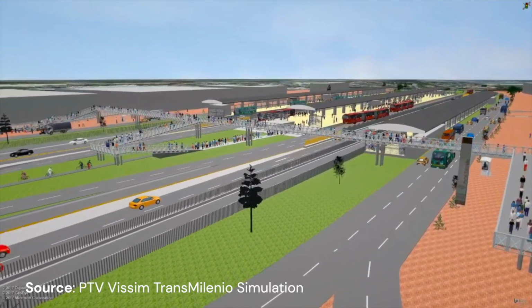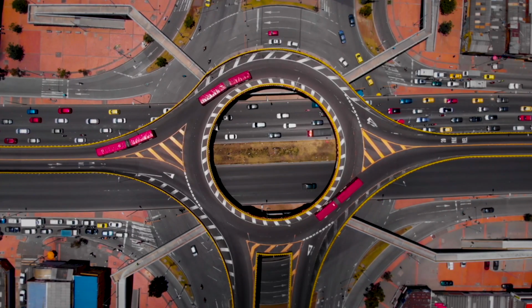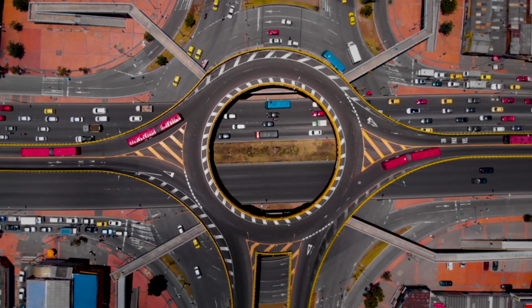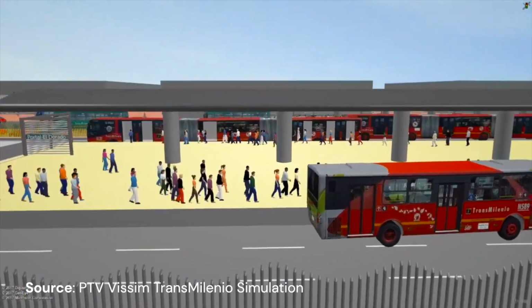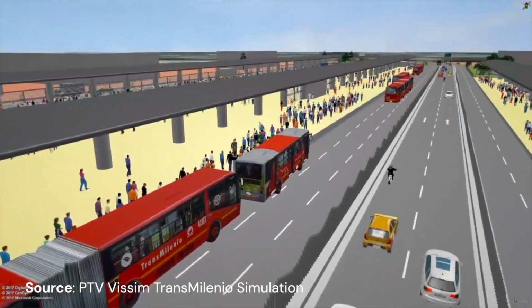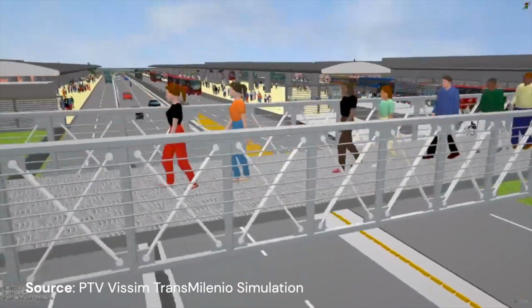And I should have some examples of stations. This is a multimodal station in Colombia, where they have the Transmilenio, a very famous BRT. And you can see how this tool may have been used for the design of the station. You have passing lanes so buses don't bunch up, which is good. You need to have platforms long enough to cater for the demand.